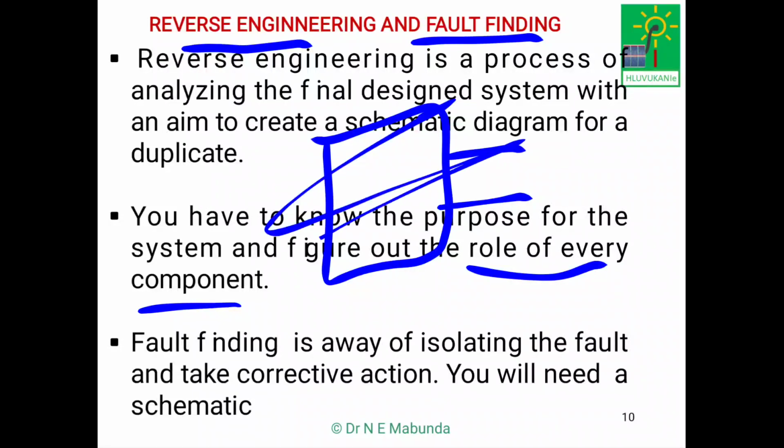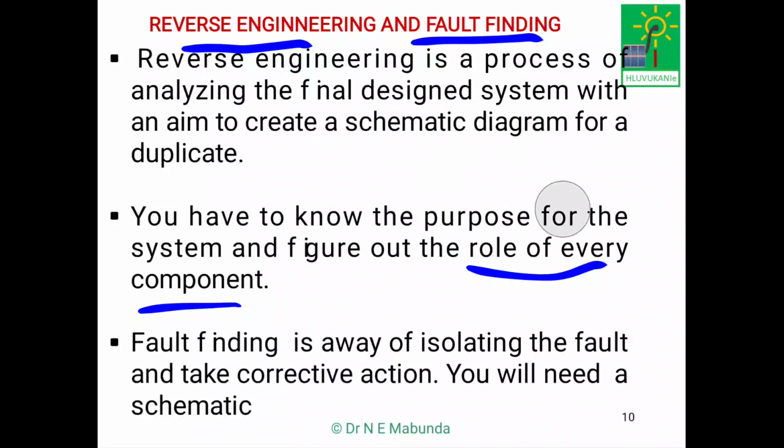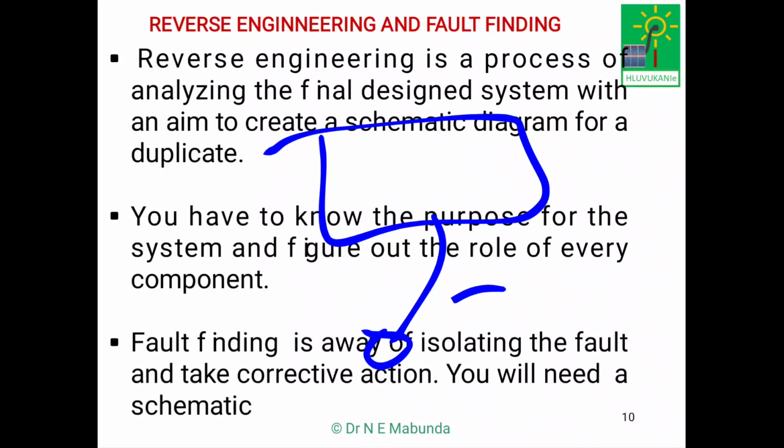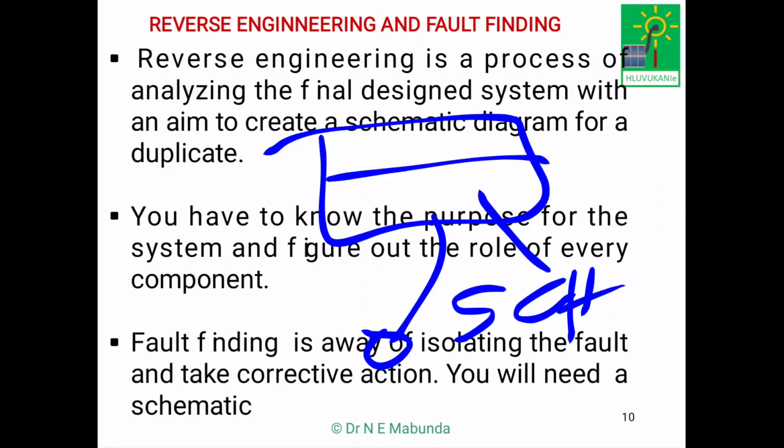And in this section, they are talking about reverse engineering. It's simply working from a board back to a schematic. We said you use a schematic to build a board, but in this case, you take an existing board and sketch a schematic from it.